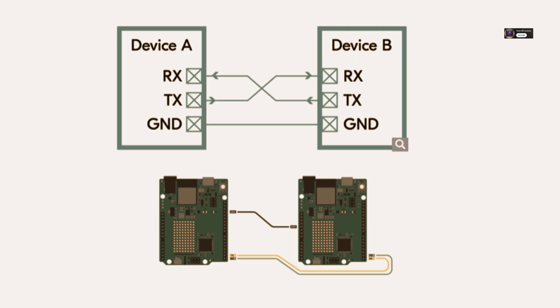Talking to yourself. Exactly. Another easy check is using that serial terminal software on your PC with a USB to UART adapter. Write simple code on your microcontroller to just print a message like "Hello World" out the UART when it starts up. If you see that message appear correctly in your terminal with matching baud rates, TX is working. Then maybe add code to echo back any character it receives. Type something in the terminal, see if it comes back. That tests RX.